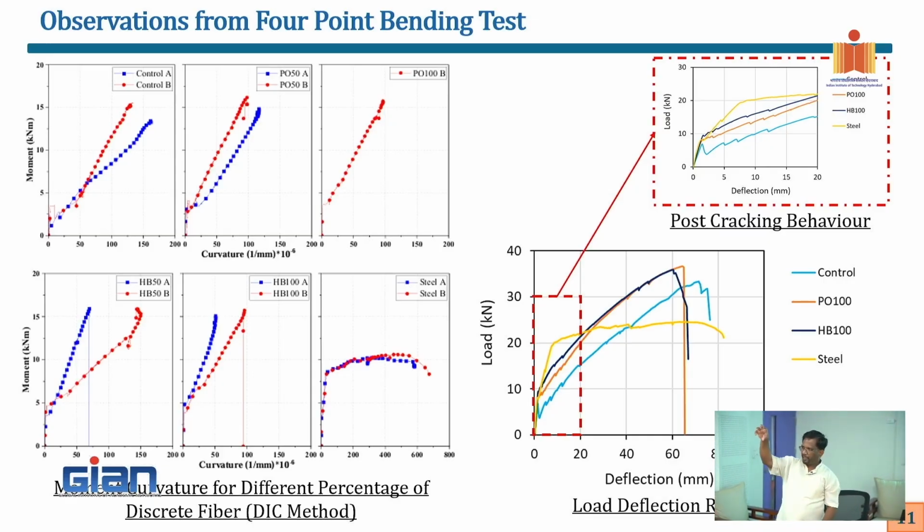So for the same kg, I get 4 times the area of the bar that I get for steel, right? So if the cost is doubled, you said two times, yes. So even if I double the GFRP rebar, the cost will still work out to be the same. You understand the point, right? Because the density of the material is less. So that's what we are looking at.